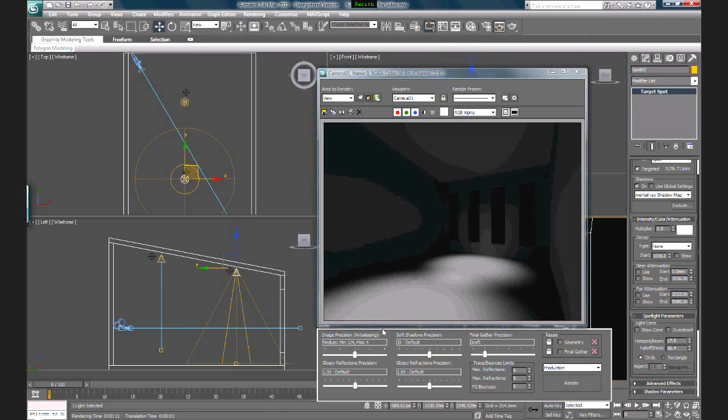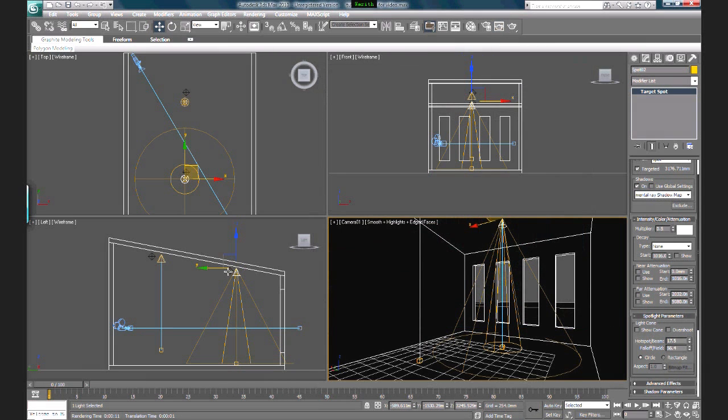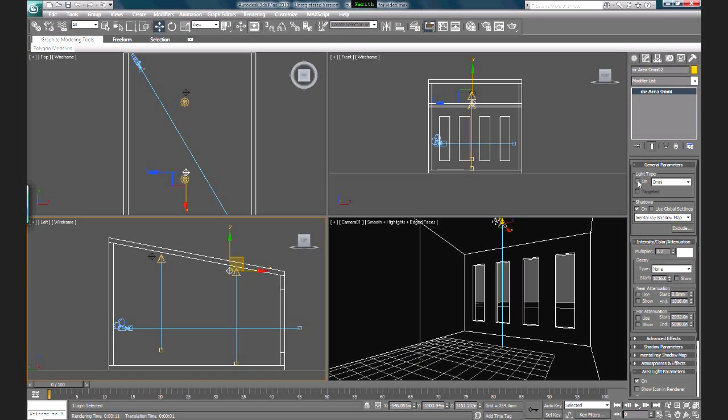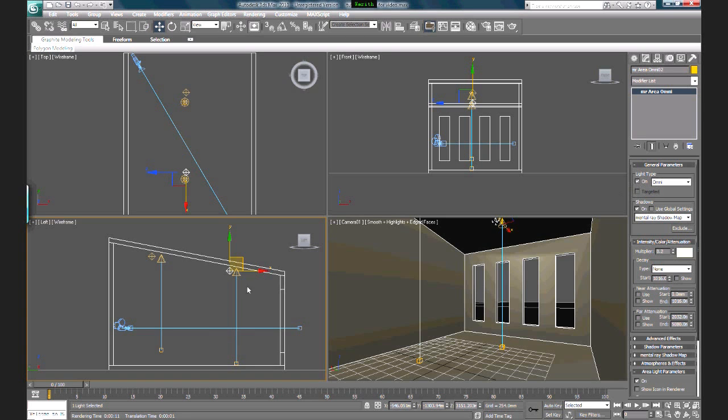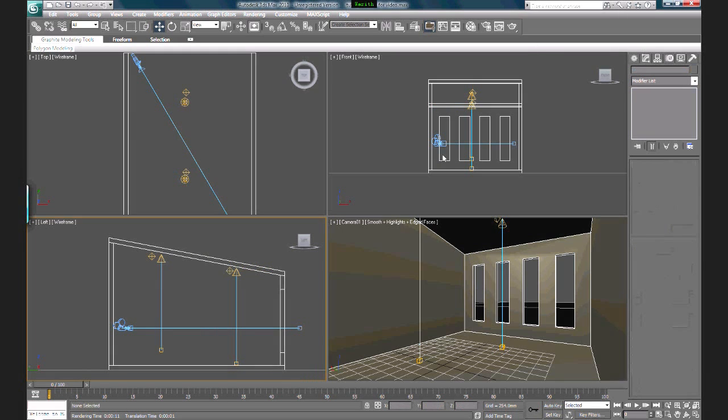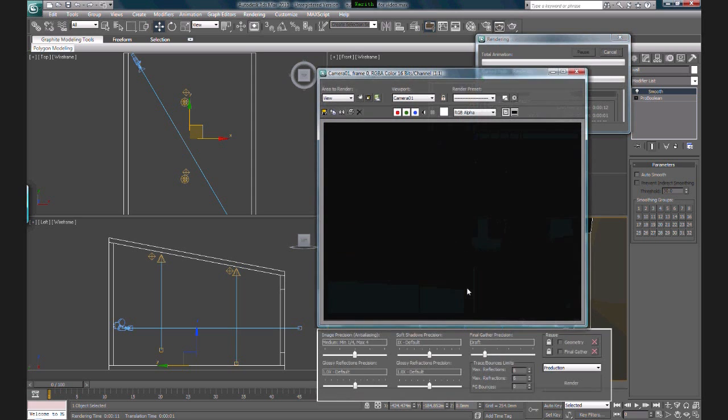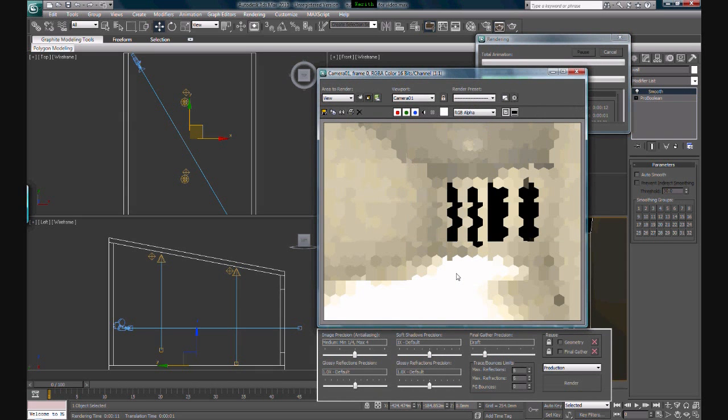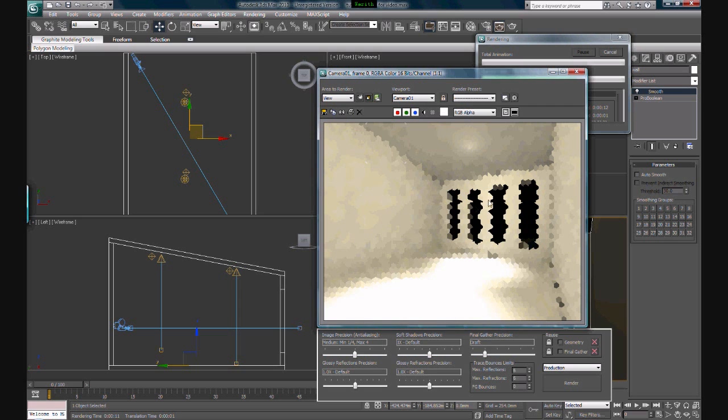It's pretty dark right now, so you can supplement your scene by inserting an Omnilight. Alright, so we can just go back to the Omnilight and turn it on. Right, maybe it's going to be a bit too bright because we have 4 lighting sources now. So if I render, yeah, it's a bit too bright, but we can see the effect of the Omnilight together with the spotlight here.